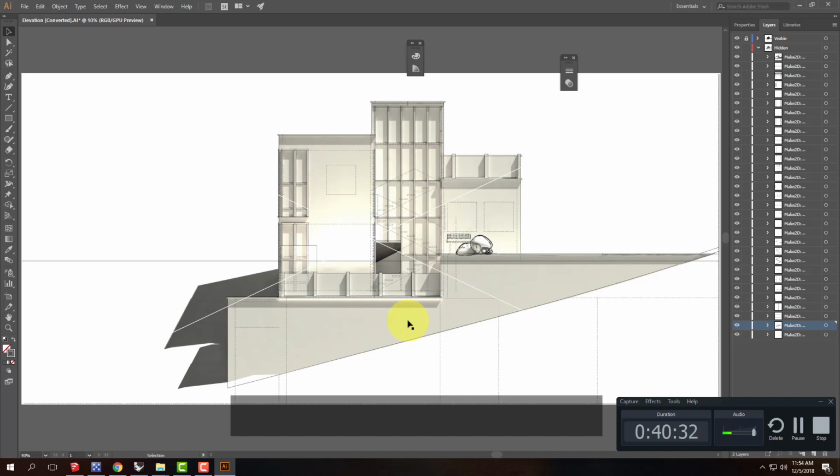That was when I did the export from Rhino to Illustrator. So when I said 48:1, that was 1/4 inch equals a foot. So if you wanted it to be 1/8 inch, basically whatever value it is, you have to be able to type in that particular scale when you do the export. So this drawing right here is actually a scale drawing that you could put up on a board and use a scale on and whatever. So it's a real drawing. It's not a Photoshop collage where you don't really know the scale. This is a real legitimate elevation drawing. And I think that's a really important distinction that you can get out of this process.